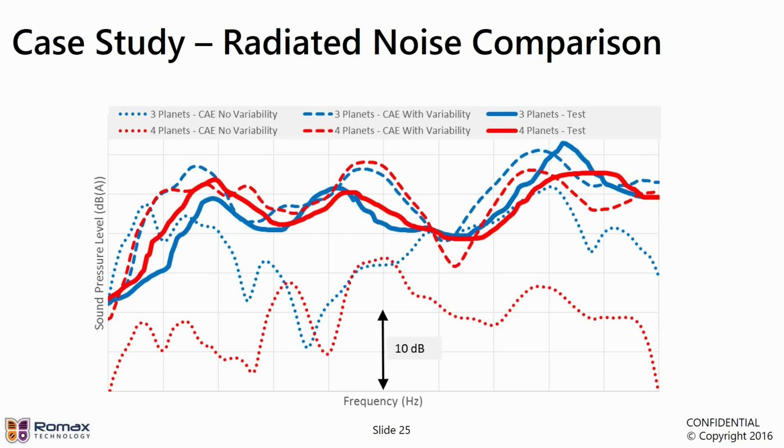In this particular case, there was quite a significant ovalization as well, a flat part to the pitch error, so it wasn't just a once per revolution, there was a twice per revolution component to that pitch error as well, and that's also very, very common in ring gears.